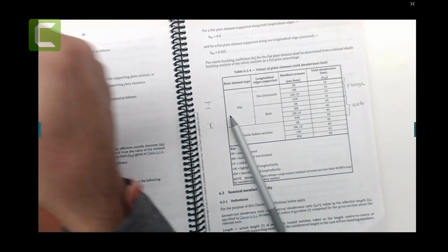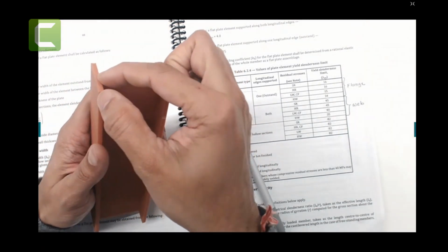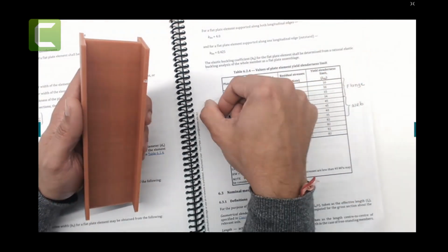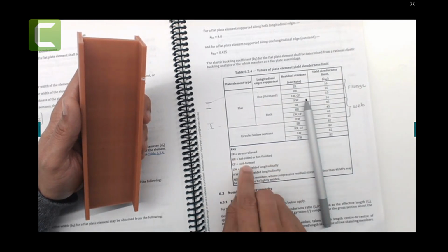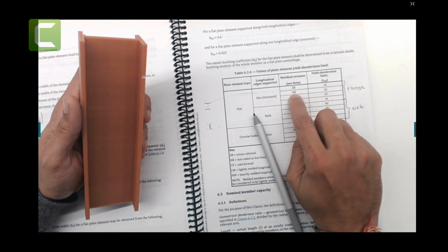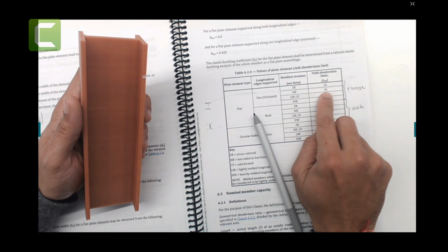So that is talking about flange, because you can look at this one here, that this longitudinal edge here is fully supported. If you look on the screen, this longitudinal edge is fully supported, and this is the outstand. That's what they talk about. One longitudinal edge is supported, and that is your flange. And here all this notation is given: stress relief, hot roll, cold form, lightly welded. All your one steel tables, one is the hot roll. So that is HR.